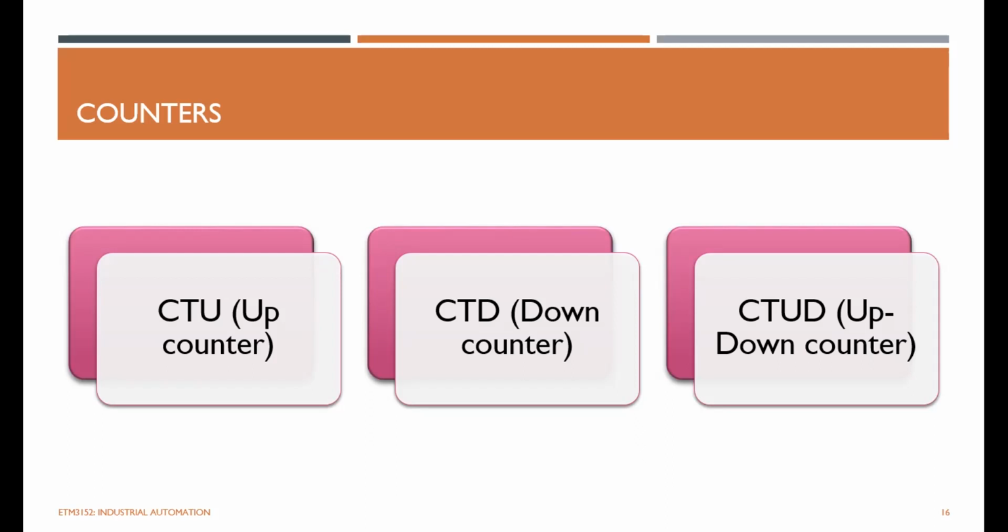For example, if you want to count people entering a supermarket, you can add an IR sensor at the door and then couple that IR sensor to the PLC, and then you can insert this counter module in software. You can just count the number of persons who entered the supermarket. Similar to that, we can implement different types of examples, like a vehicle parking system, the number of vehicles entering the parking lot. Likewise, you can just add the counter to a simple push button, and once you press the push button, you can count the number of attempts like that.